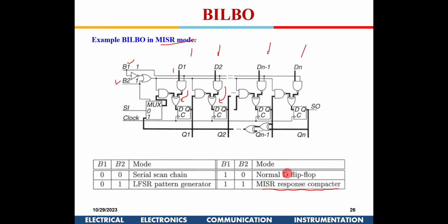So for any system, first chip wise, then PCB wise, and then system wise, it would run a built-in test. So there is no manual intervention required. Test bench and connection to the test bench are not required. All this will become part of the circuit. Now this built-in test also takes into consideration the scan design.